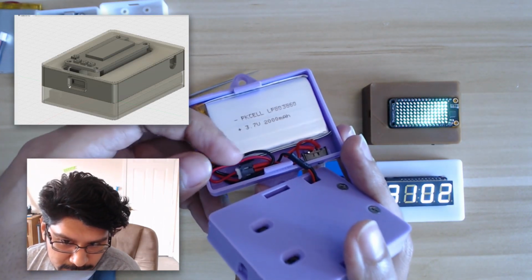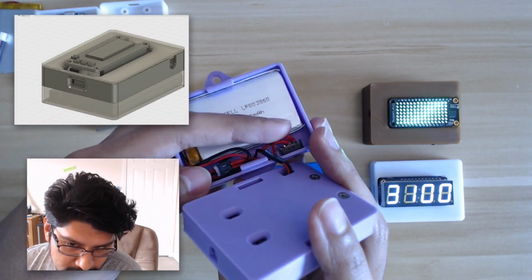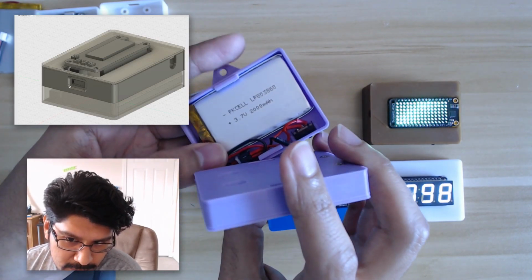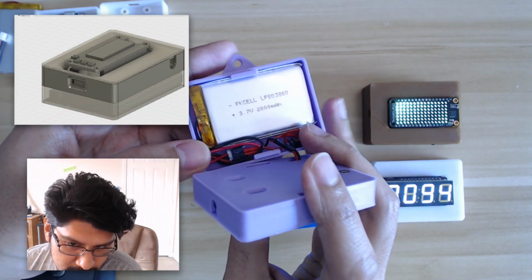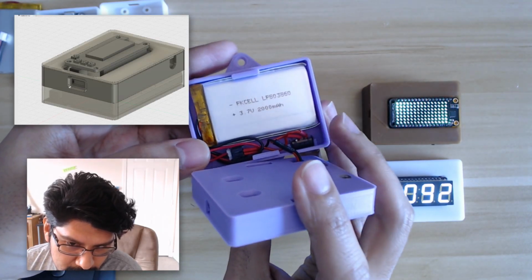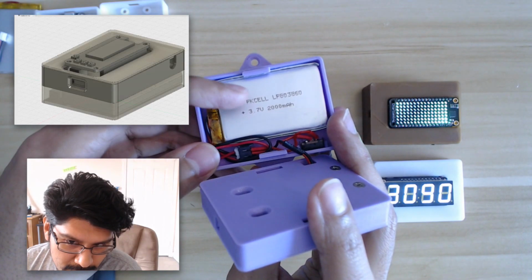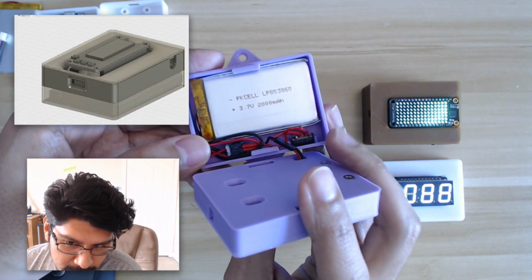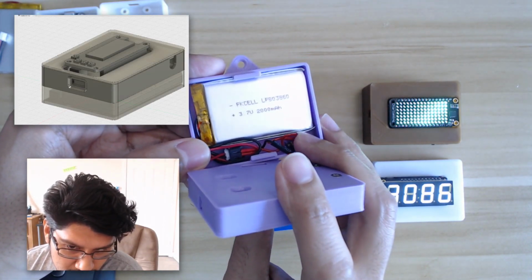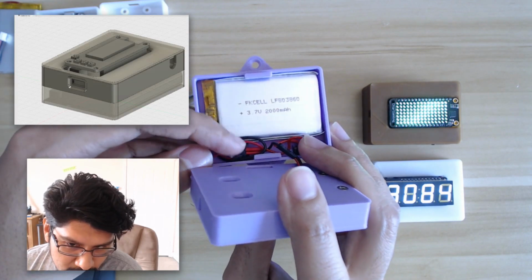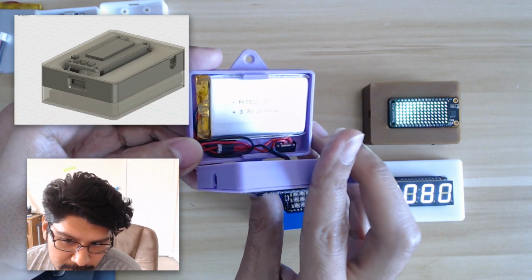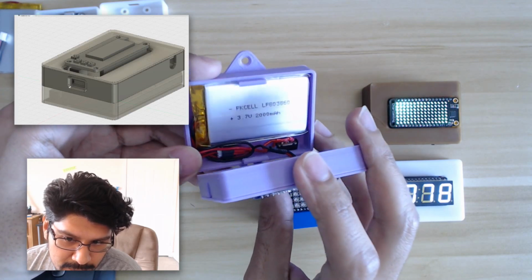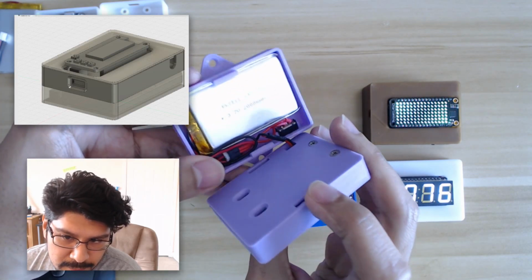All this wiring here is for the switch. So there's a little switch here that can turn the battery on and off. And wired to the switch is a male and female JST connector. So the idea being that you can disconnect the battery easily. We could have soldered this switch in line with the connector from the battery, but I'm not a fan of cutting wires from the battery. Of course, you could do that, but I don't like to do that too much.